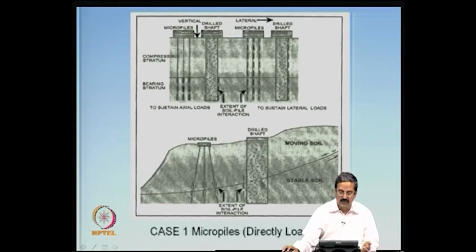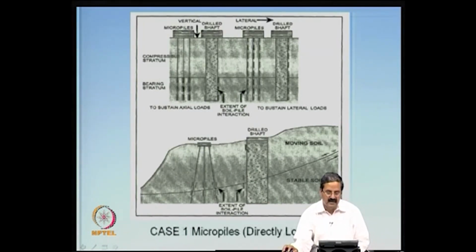And if we know that the soil is poor in shear resistance, and now you have a concrete column here, even with steel reinforcement, they can be very good in resisting shear. So, you choose the diameter of the pile such that this provides resistance. Earlier the factor of safety is less than 1, now you have a bigger diameter pile, and if you are able to properly design it, this shaft is sufficient to take care of the slope. But as I just mentioned, instead of this shaft, one can even have simple micropiles like this.